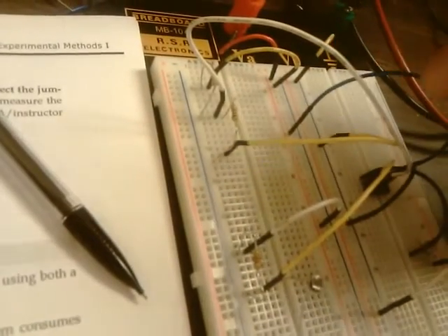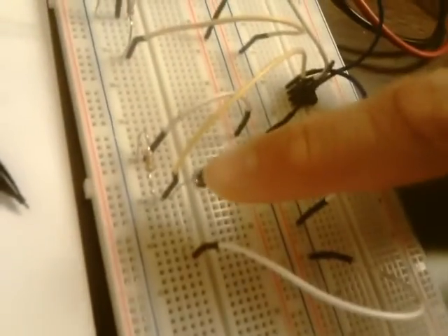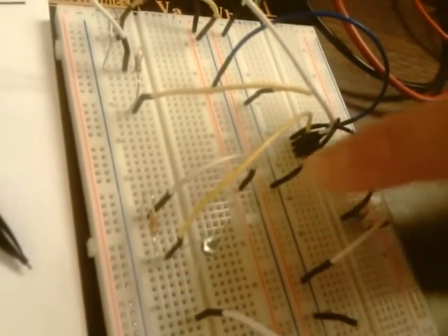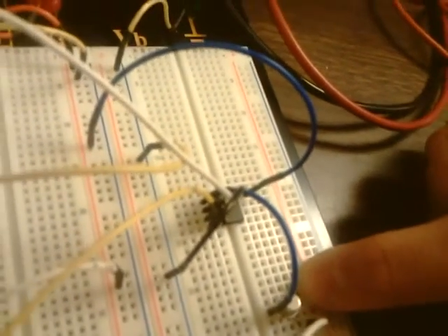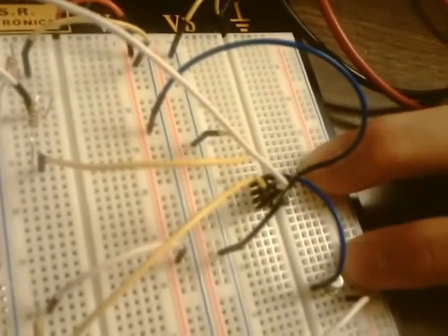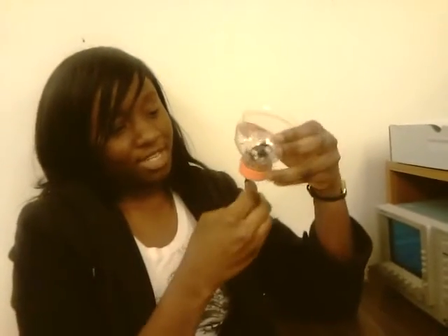So here we have our completed circuit, and we have the op amp right here. We have our transistor right here. We have these two areas right here, which create the two different voltages that go into the op amp. This is our light dependent resistor, which is going to control this whole voltage right here. And we're going to connect the light bulb to this side of the transistor and V out on the op amp. So I'm going to connect the light bulb. This is the positive side of the light bulb, and that is the negative side.